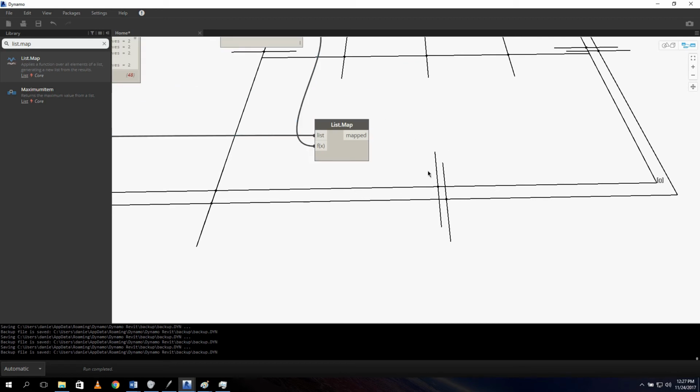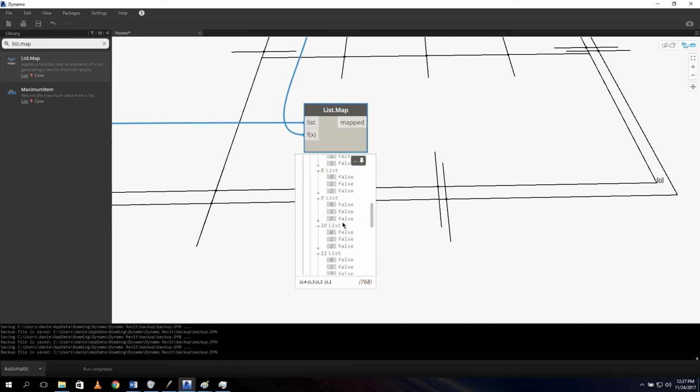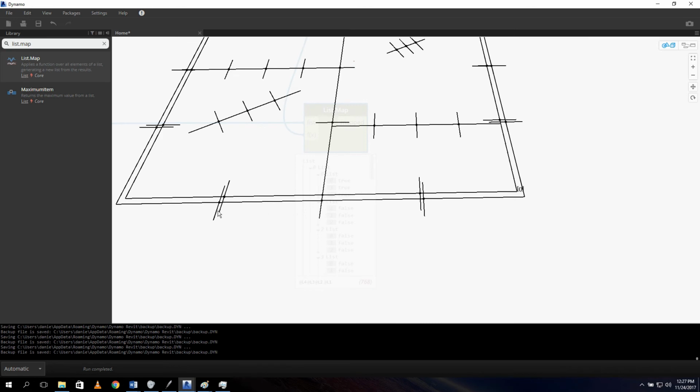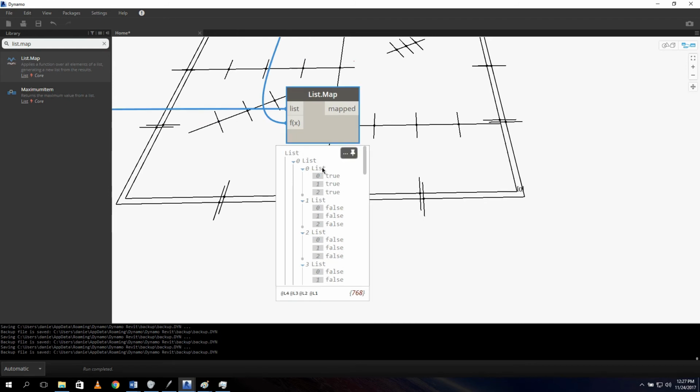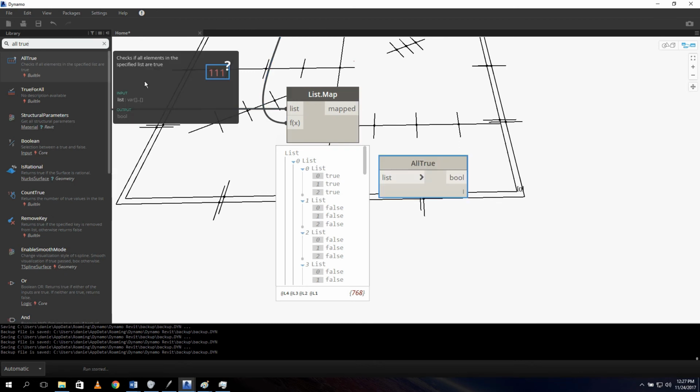And now the first thing we need to do is to make sure the wall is over there, and we're doing that by using our lines. So we can see, for the example, the output is true, true, true. It means that all 3 detection lines are in the wall. If something is false in the same list, it means it's only in 2 intersection points or in 2 detection lines. And that's not what we need. We want the wall in all detections. So we say all true.